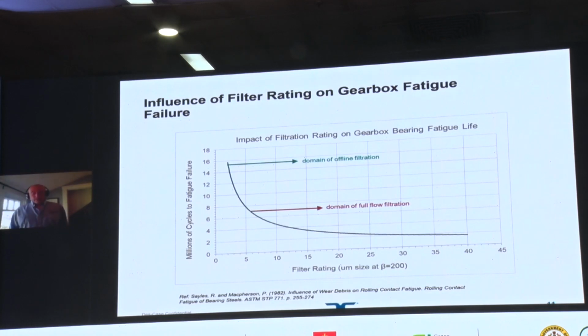With particle contamination, we want to make sure that our full flow filtration is in good condition and that we are using the most effective filter we can. But by supplementing the full flow filter with an offline filter, we can really look to extend the life of our gearbox and to extend the life of the asset overall. So my encouragement to you is do some research, go ahead and look at ways to install supplemental filtration, talk to the Des-Case people that are at the wind turbine conference there, and let's see how we can support your reliability efforts through upgrading your filtration and contamination control.